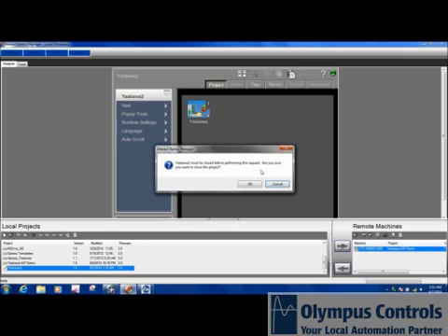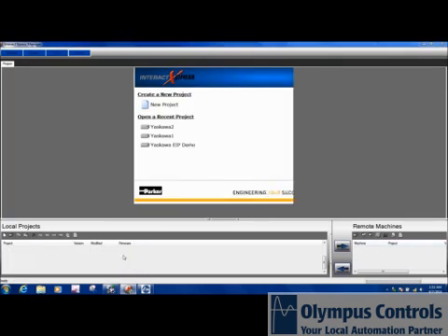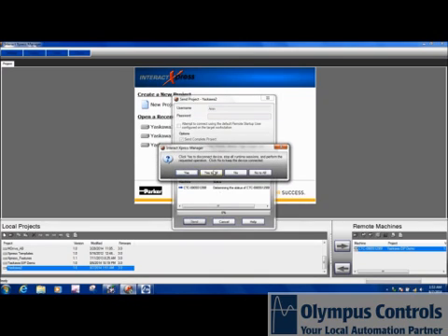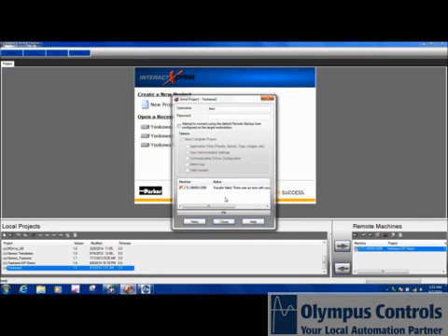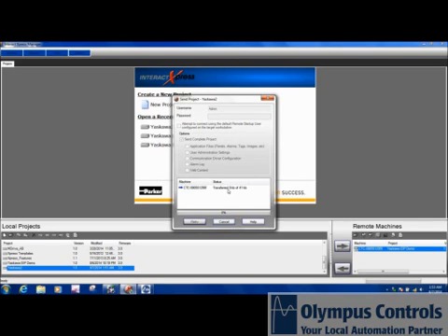I simply click the send button, and it says, you must close this current project, which is also going to save it, and then it will copy this project over to the actual touch panel. So I log in with my admin username, password is blank, and I hit send. Yes, I want to send all parts of the project over. Oops, I spelled my password wrong here. Try it again. There we go. It will transfer the project.